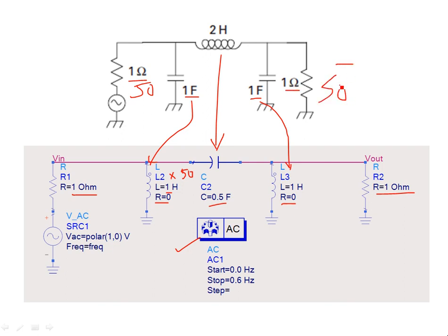And well, if you don't have the same reactance, same load and source impedance, you might need to include LC matching sections for that, right? You have to do this with the impedance matching networks. Okay, we are not going to get into that. There are some video lectures, you can go and watch them for LC matching and for pi matching or T matching networks. We have different topologies for impedance matching networks. But if the impedances are different, you have to consider an impedance matching network in between, right?